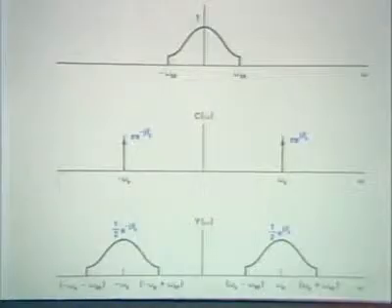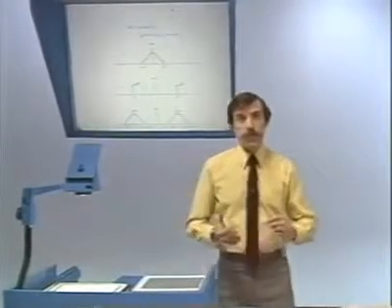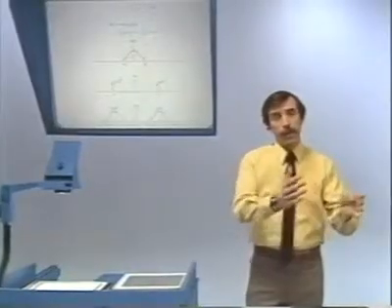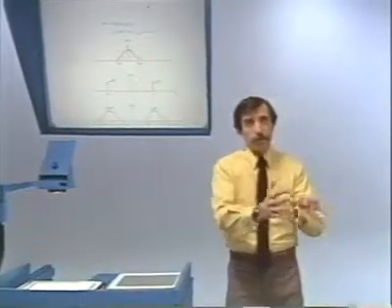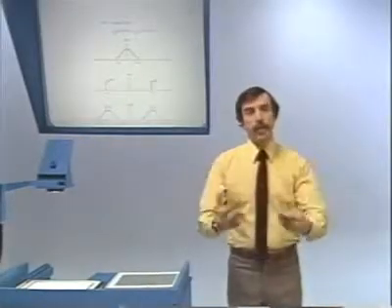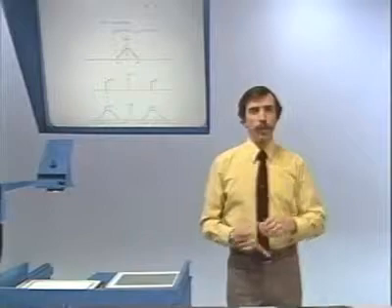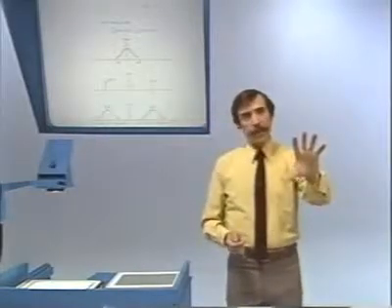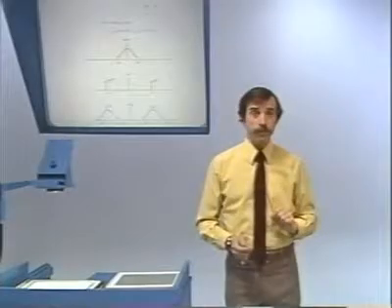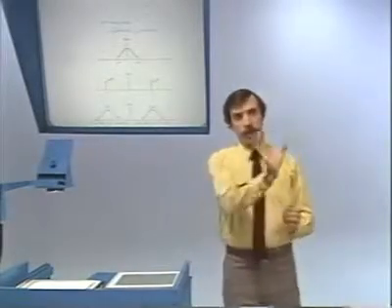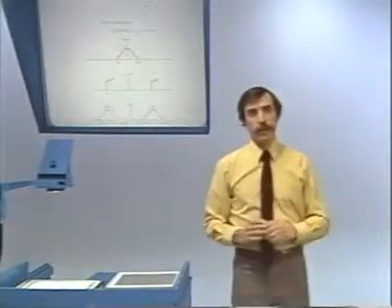Okay, well, now what's happened is that with a sinusoidal carrier, we've moved the spectrum to both plus omega c and minus omega c. And if we want to get the original signal back again, what we would like to do somehow is move that spectrum back down to the origin. In the case of a complex exponential, that was easy to do. We had shifted one up, we just shifted back down.